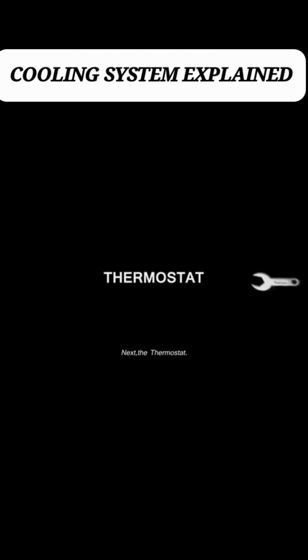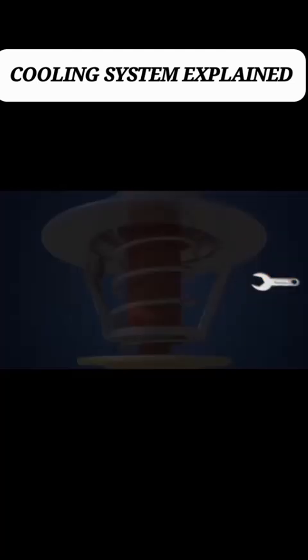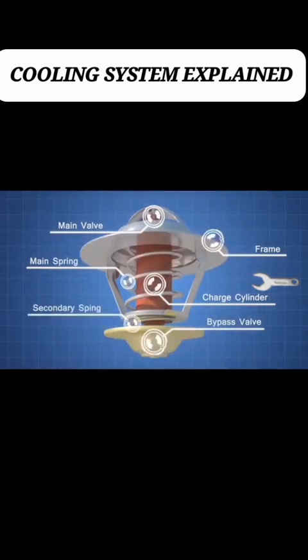Next, the thermostat. The thermostat is a valve which regulates the flow of the coolant, and helps to maintain the proper operating temperature for the engine. The thermostat consists of a frame, charge cylinder, main valve, mainspring, bypass valve, and secondary spring.